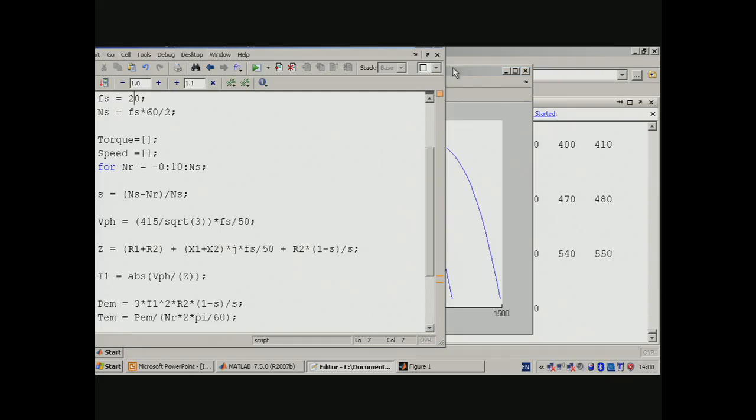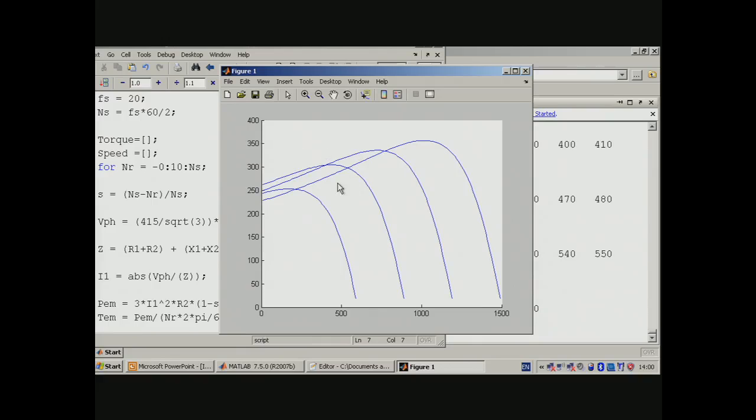20 hertz and so on. So you don't have an increase in peak torque, so the peak torques are fairly in a roughly similar range. The important characteristic of this V over F control is the region where you're operating around here. If you look at these lines, they are parallel to each other. From here to here, it's parallel to this, all around this region, it's parallel to each other. So we are interested in that characteristic when you're operating V over F control.